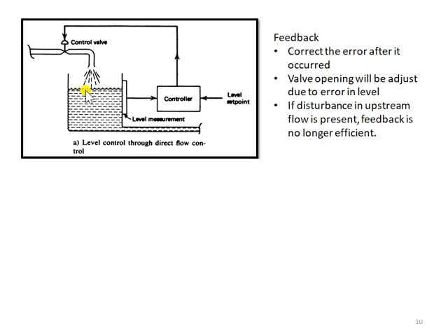Once the level has increased to the set value, the controller will send a signal to the control valve to reduce the opening to make sure that the water level is maintained at the set value. So this loop will be repeated over time.